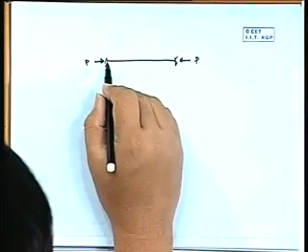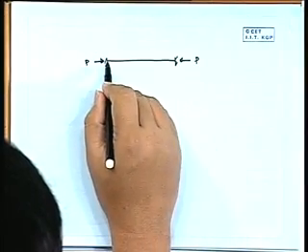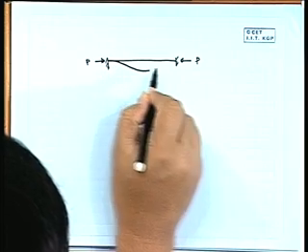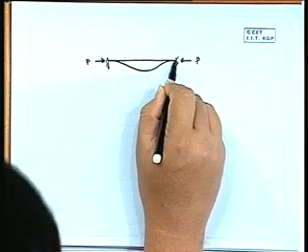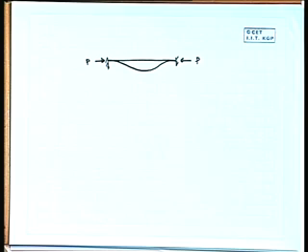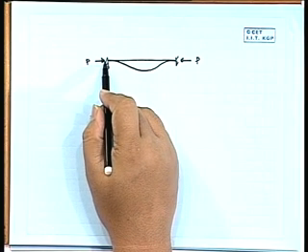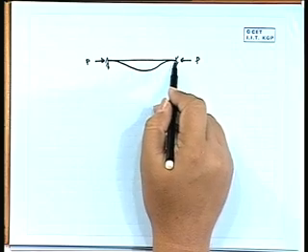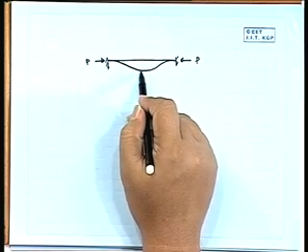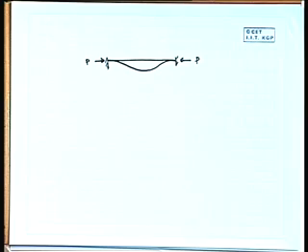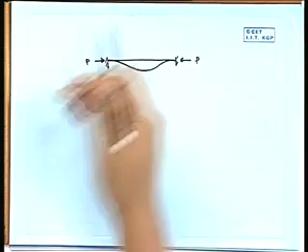Now if we draw the deformed shape, the fundamental one, so here slope will be 0, it will be maximum and it will go like this. So here it is clamped, there will be no deflection, no slope. No deflection, no slope, it will be maximum, symmetry, slope will be 0, so the shape will be something like this. So why can't we think that it will go up? Okay, it may go the other way also, okay.